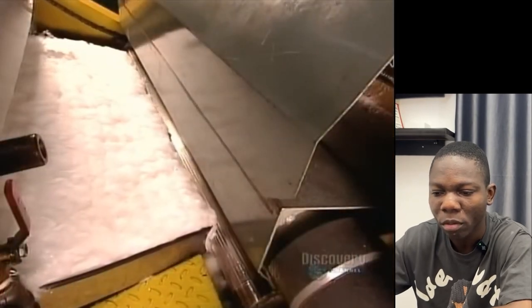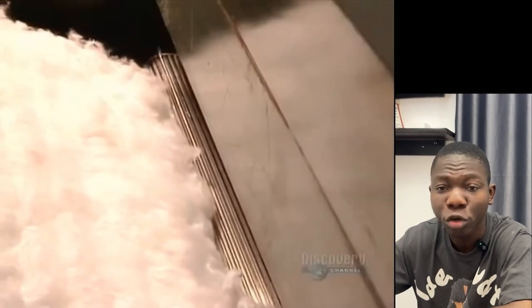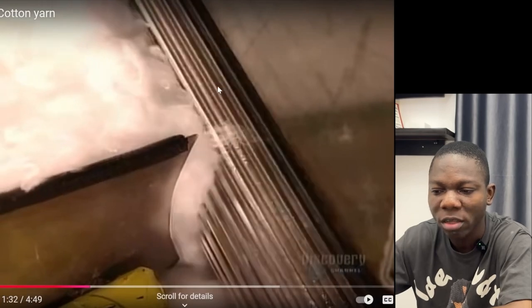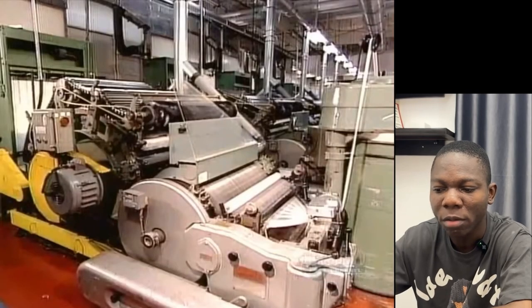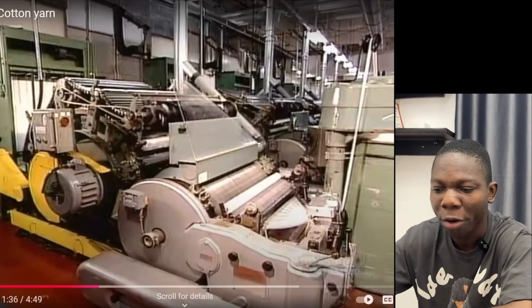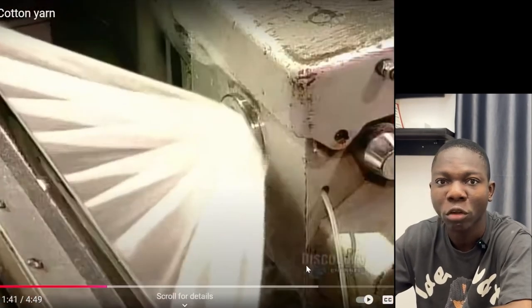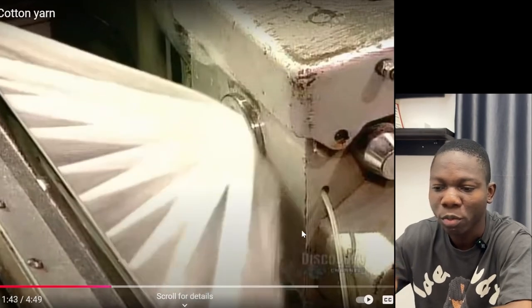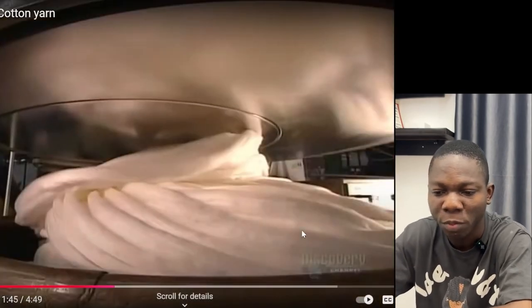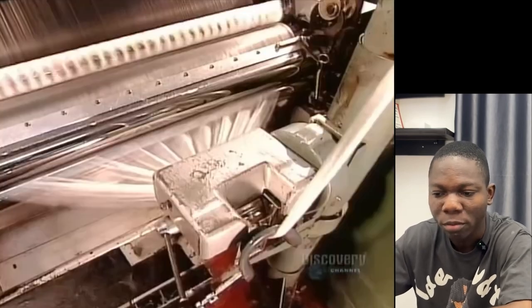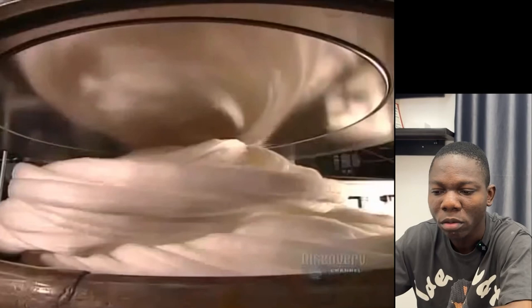Now the cotton goes through what's called a carding machine. This is going through a carding machine now. Rollers with wire teeth untangle the fibers and line them up in pairs. It's also discarding and removing any short cotton and putting them into rolls. Then it forms them into a first stage yarn called sliver.